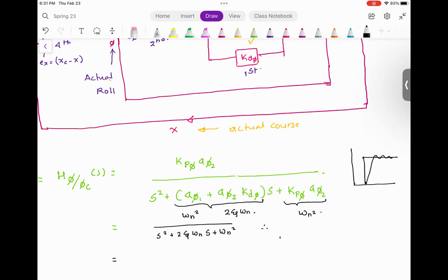And if you have your simulation working correctly, you will observe this. If the aircraft is in level flight, everything is fine, it will work fine for some time. But then if you have wind terms coming in, because of the wind, first the aircraft would change the course. And then the aircraft will roll. And then because of this rolling, again it would change the course. And then it would roll. And finally, it would crash.